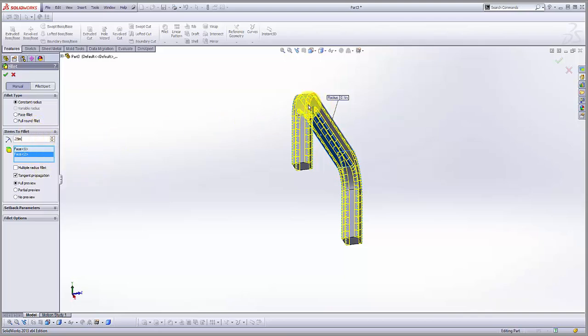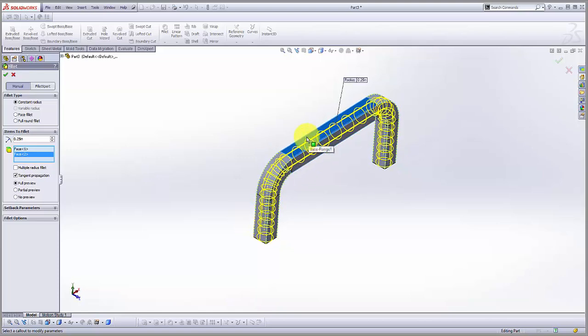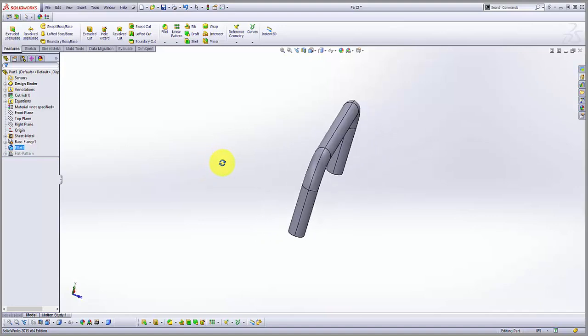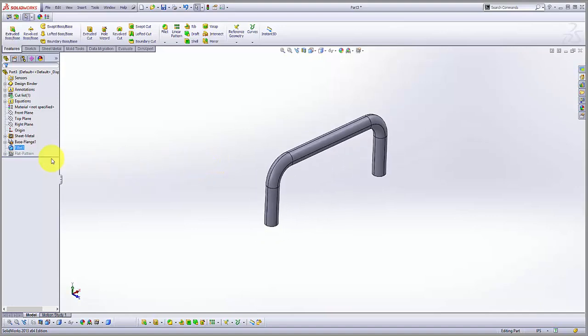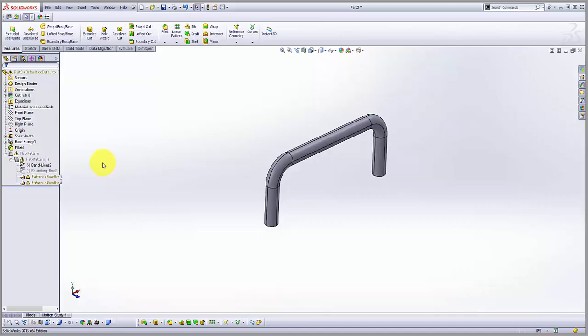So if we do the fillets to a 1/4 inch, which is half the dimension, so 1/4 inch here, 1/4 inch here, that equals 1/2 inch. And we make this a round bar, when we try to unsuppress the flat pattern, we get errors. Why do we get errors? Well, my guess behind the errors is that it's because SolidWorks likes flat surfaces for sheet metal.